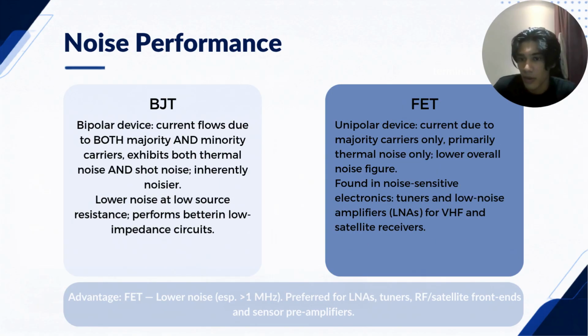Now, moving on to noise performance, BJT inherently produces more noise because it is a bipolar device where current flows through the majority and minority carriers. So it exhibits thermal noise and shot noise.